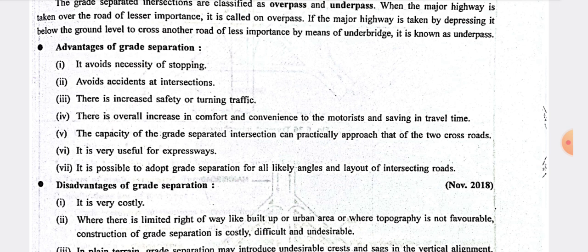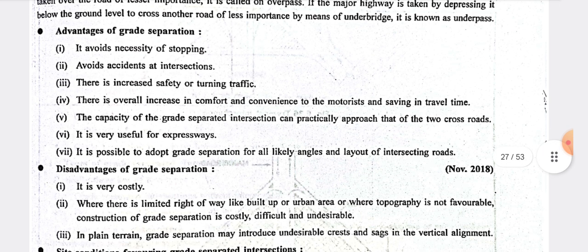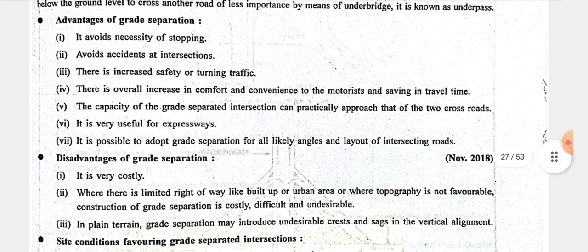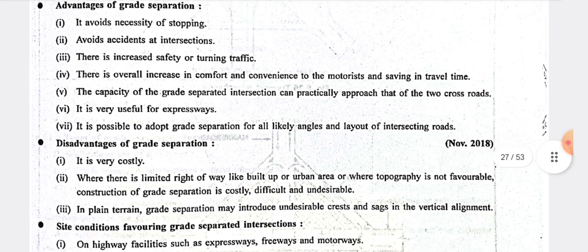Here are some of the advantages of grade separation. First, it avoids unnecessary stopping, because in grade separation we move the traffic in underpass or overpass form. Second, it avoids accidents at an intersection. Third, there is increased safety for turning traffic. Fourth, there is an overall increase in comfort and convenience to motorists, and it saves travel time.